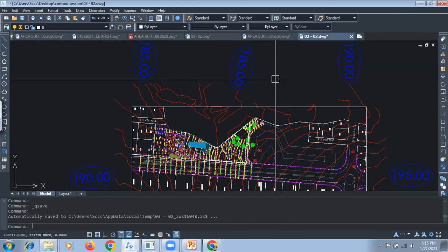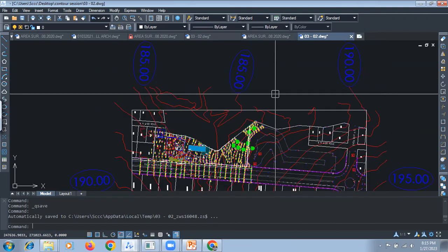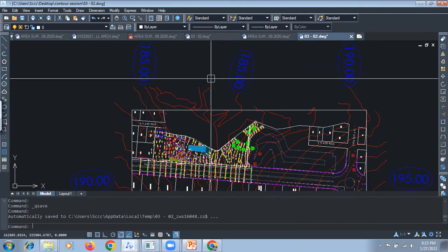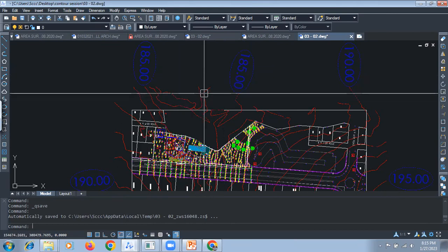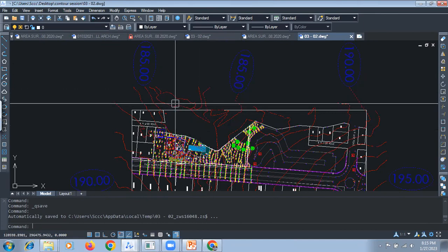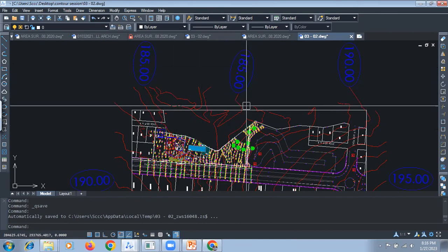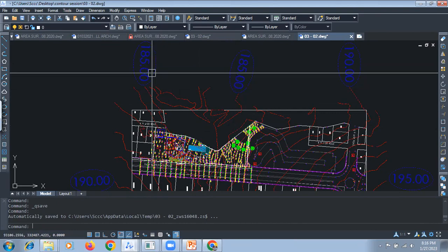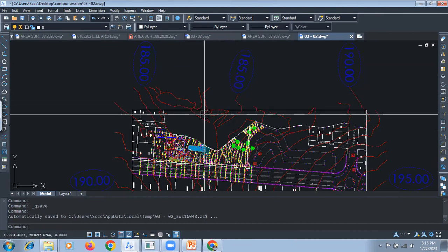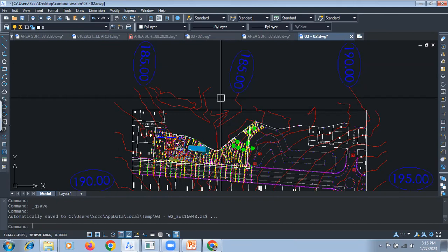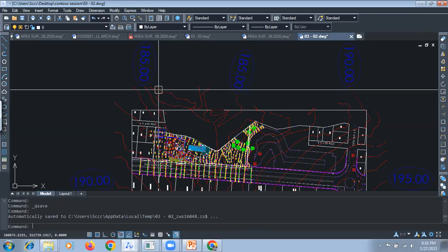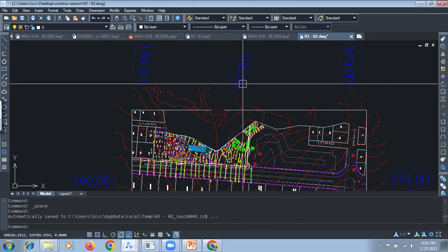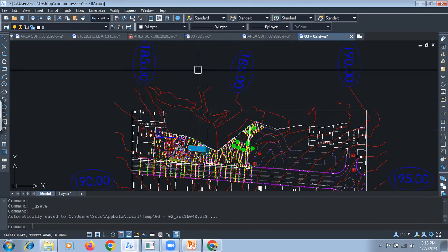No, no guys. There are two chances. It cannot be flat first. Why? Because already some contours are shown in this particular area. If it is exactly flat, then your contour should start here and here. There should not be any contour in between. So what are the chances? Either it is a hill or it is a valley. Either it will go down, then come up again here, or it will go up and then come down.